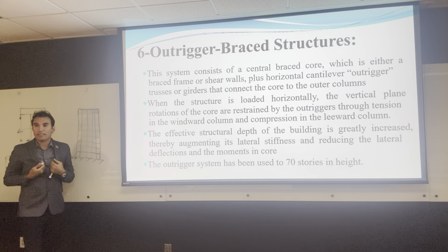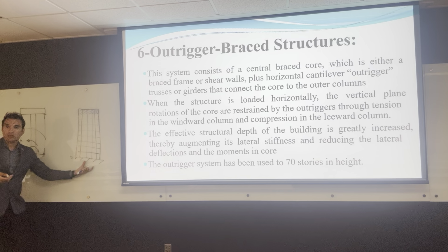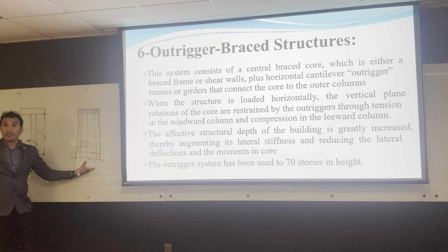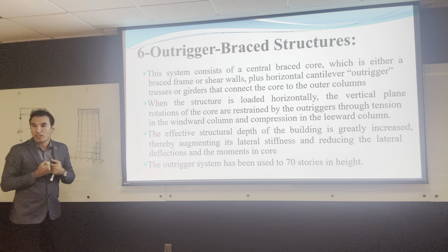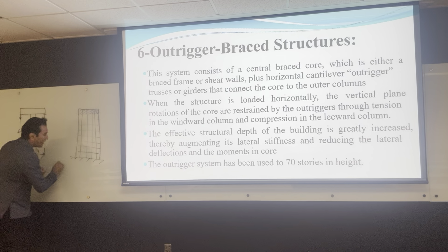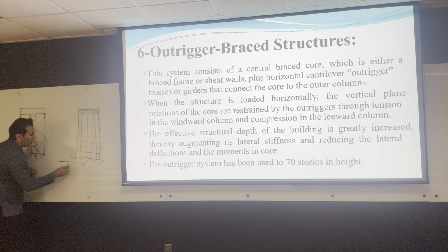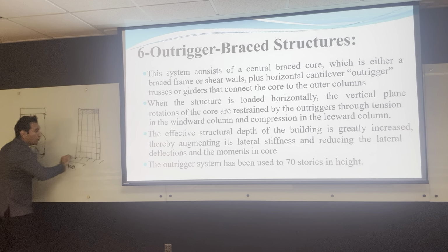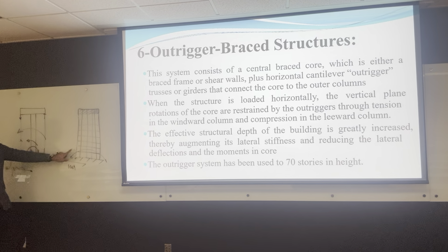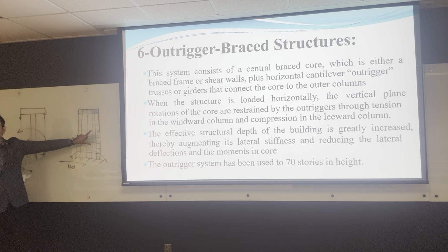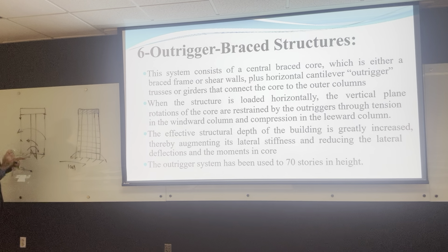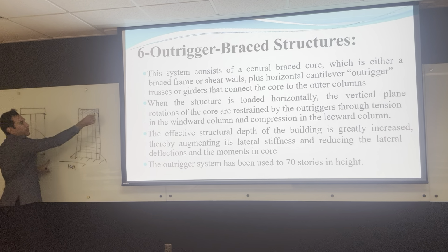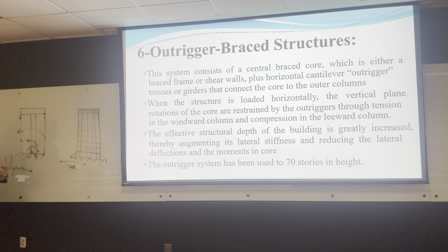So what we did is we reduced the bending moment on the shear wall, or the shear wall can take bending moment, but we add more resistance by making the columns take more forces from the earthquake. Let's say that the earthquake is going to hit with a force of, I don't know, 100 tons, okay, and make a huge bending moment here. So rather than having just the shear wall resisting this bending moment, we are making all the columns that are connected here resist the bending moment. But the columns at the start and the end take most of the bending moment.